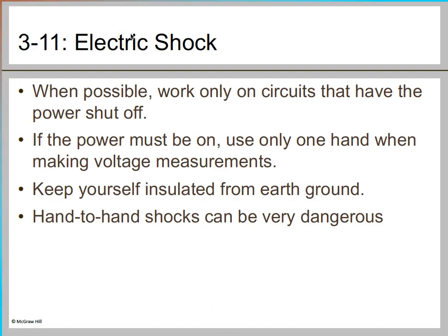Now next is electric shock. When you're building the circuit, make sure that you're building it based on the schematic provided by the manufacturer, or that you have enough knowledge about the circuit you're building. Make sure that there are no wires hanging out, which could be dangerous or may produce a shock.